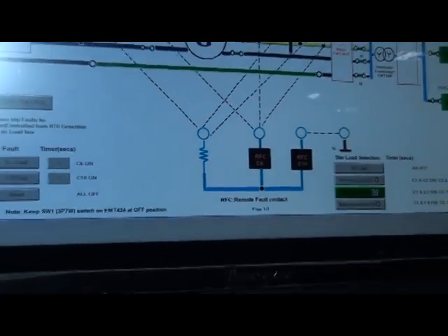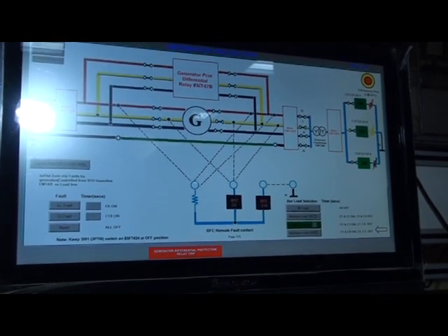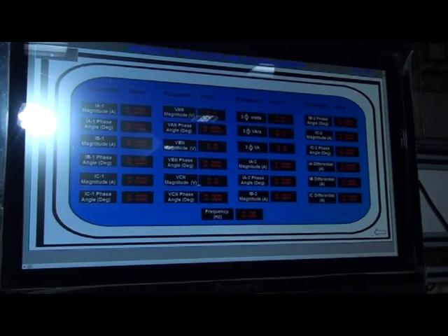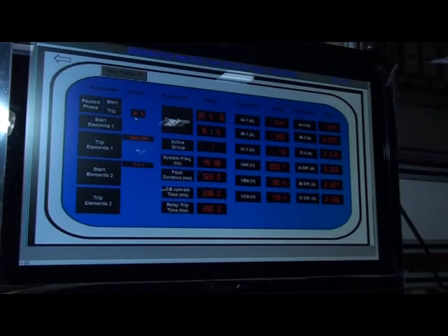Now observe the fault record. Click on the generation protection relay screen, then the measurement window opens. Then press the view record button on the measurement screen. Now we are observing fault history. Trip phase is due to B and C phase, that is Y phase and B phase. Trip element is generation differential, and also observe IB and IC differential currents are high, that is 2.3 ampere and 2.9 ampere, while IA differential current is 0.003, which is normal.